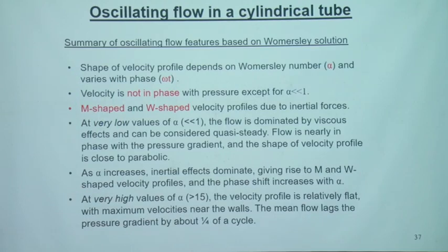Now, if you want to know more about the Womersley solutions, you can refer to the original paper published by Womersley. It's quite a long paper, and it has detailed mathematical solutions. So, just a brief summary. What we have learned from the Womersley solution is that the shape of the velocity profile depends on the Womersley number, and it varies with time or phase. And the velocity is not in phase with the pressure, except for very low Womersley number.